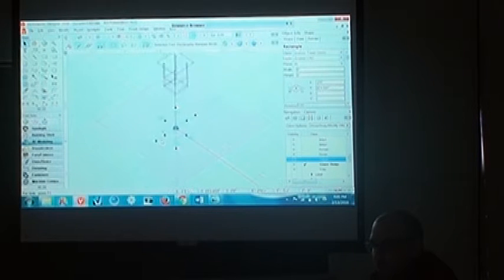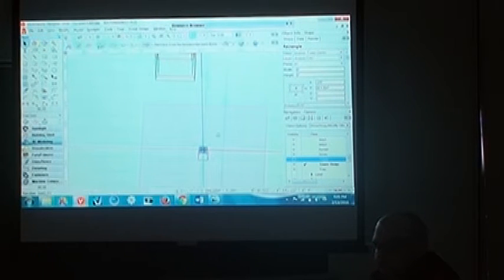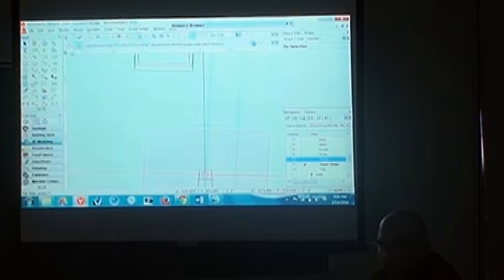So the way I'm going to do that is I'm going to do an extrude along path, but I need a path that goes between those 2 points. So the safest way to make sure I can draw a line directly between that point and the point down here is to set a working plane. So I'm going to use my 3-point mode.